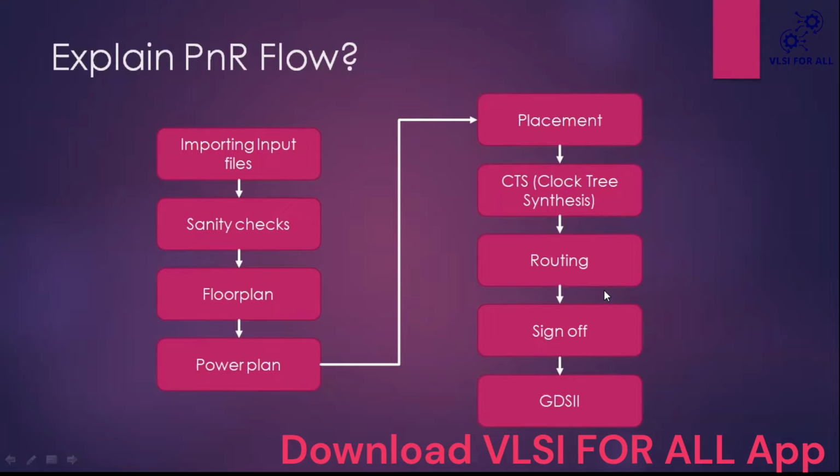If they find anything, like a DRC or a timing violation, they will tell us how to fix it, and we have to fix those violations by coming back to the PNR tool. You have to remember this.